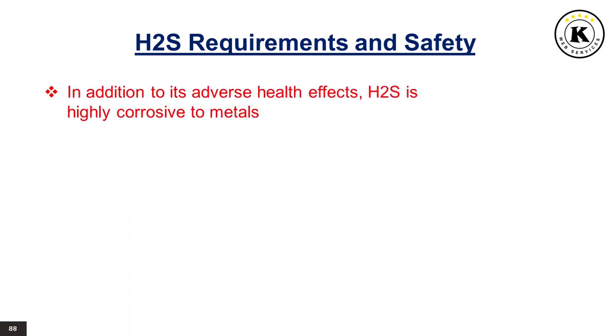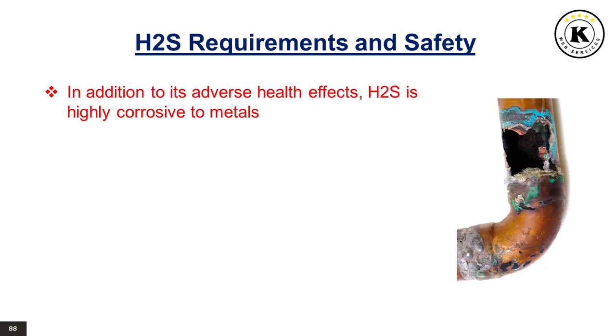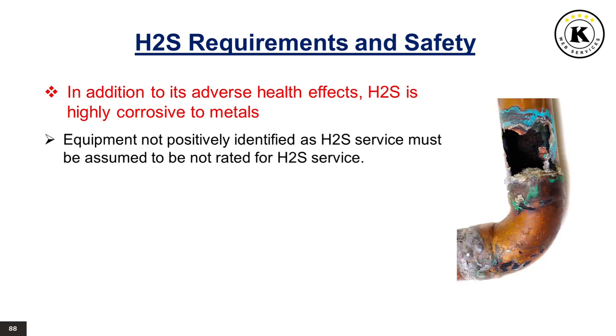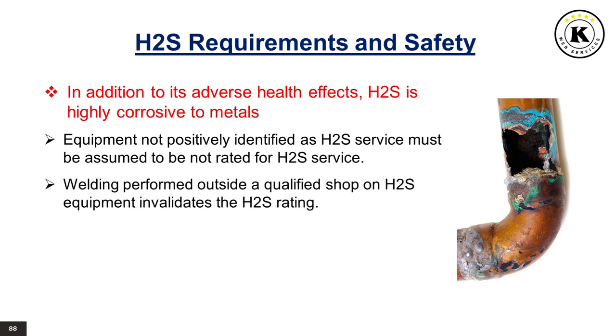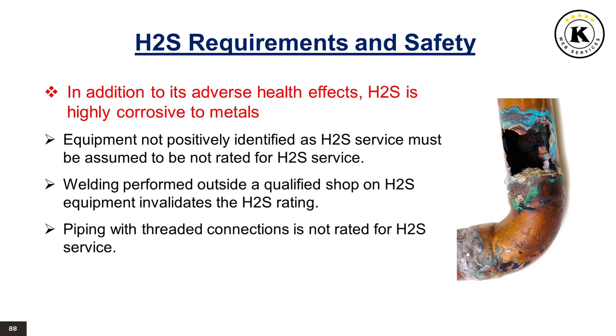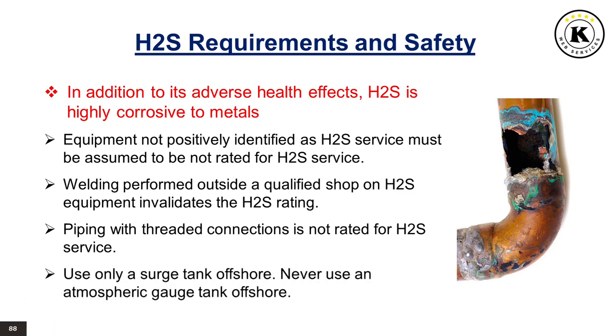In addition to its adverse health effects, H2S is highly corrosive to metals. Equipment not positively identified as H2S service must be assumed to be not rated for H2S service. Welding performed outside a qualified shop on H2S equipment invalidates the H2S rating. Piping with threaded connections is not rated for H2S service. Use only a surge tank offshore. Never use an atmospheric gauge tank offshore.